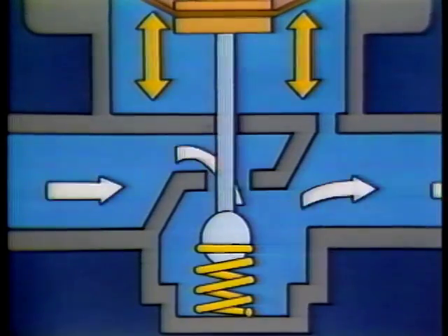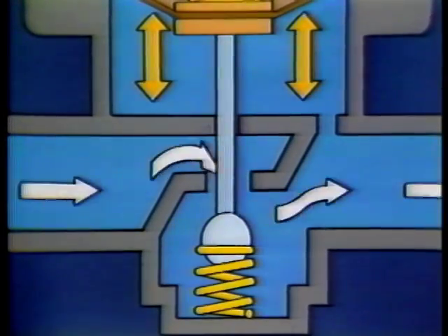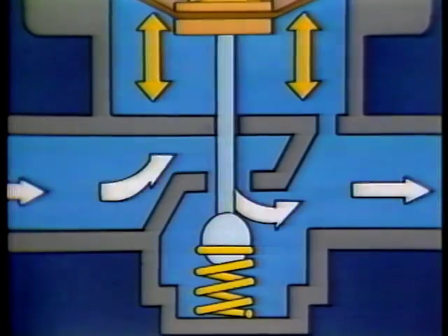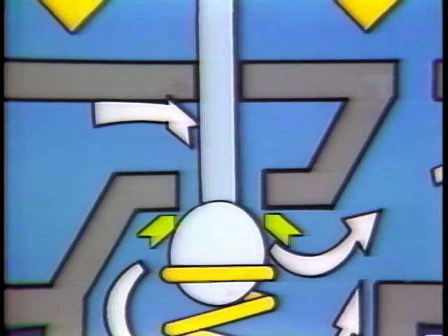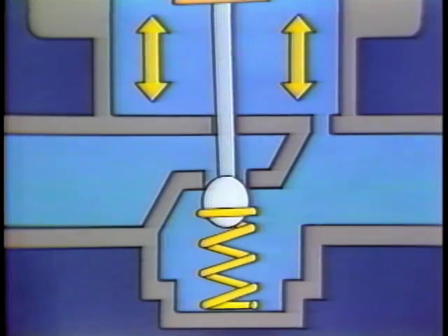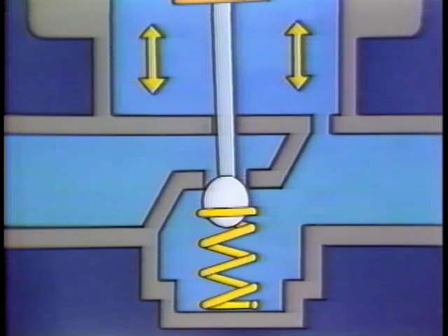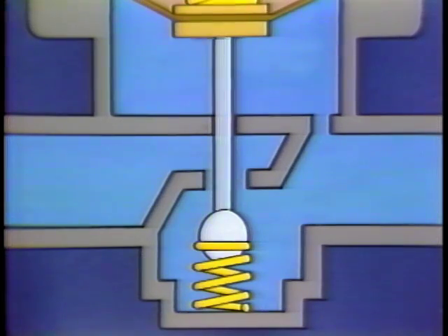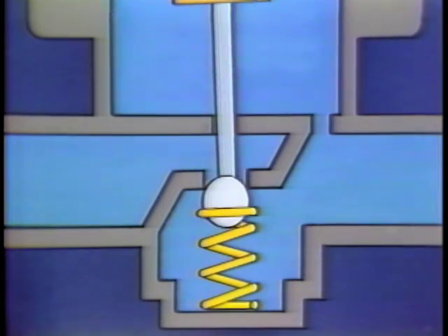A similar problem may occur with liquids at very low flow rates, even when the valve is properly configured. As the valve begins to close, its throat area becomes restricted. The pressure in the throat area drops as a result of the Venturi effect, slamming the valve into the seat. The immediate cessation of pressure in the sensing chamber causes the valve to snap open again. The valve continues closing and opening rapidly in a chattering fashion, and again, water hammer and damage to the valve may occur.